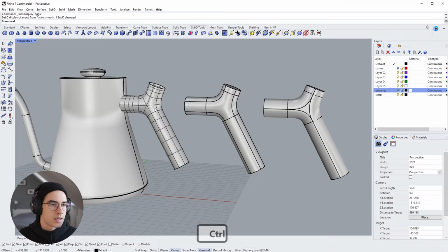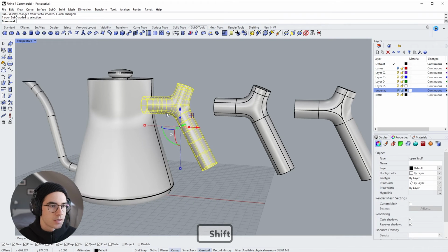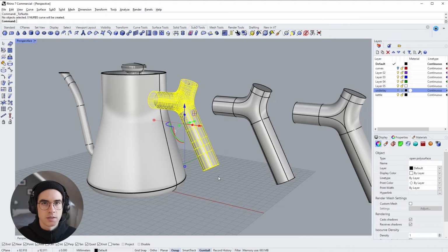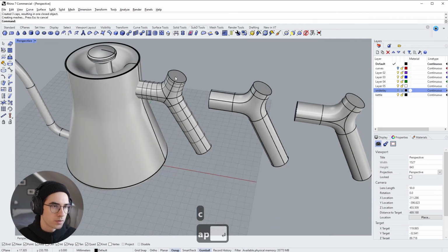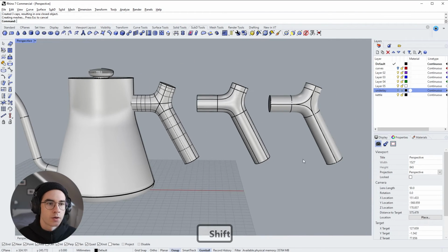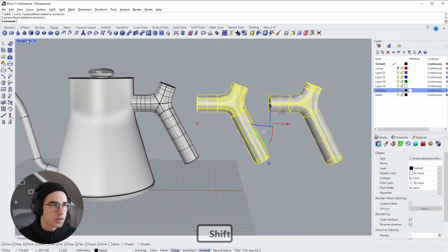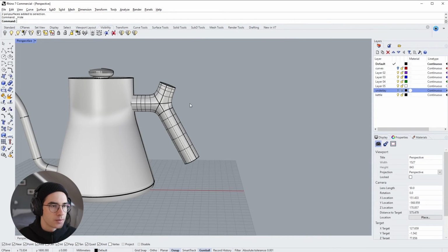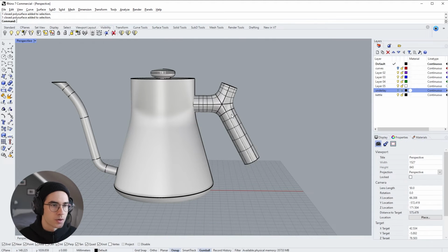All right, so then the last step now is to create surfaces, real surfaces from the subdivision element. And here is the convert objects to NURBS tool. So hit that once and hit right click. So this is now a NURBS surface part. And similar with the other ones, we can also hit cap in order to cap those open parts. So depending on which is your favorite, I'll just hide those two, and then work with the sub D one.